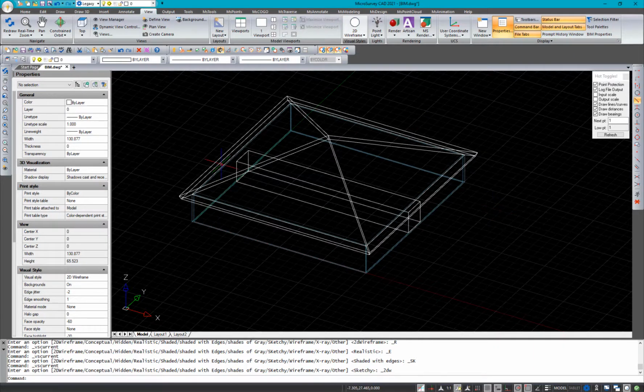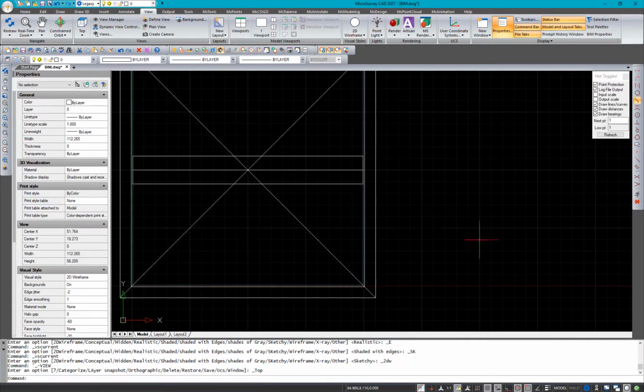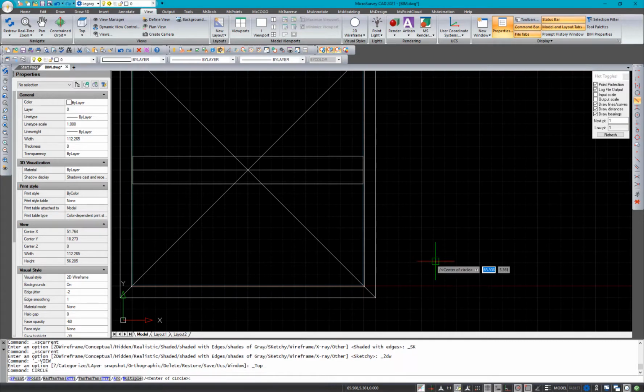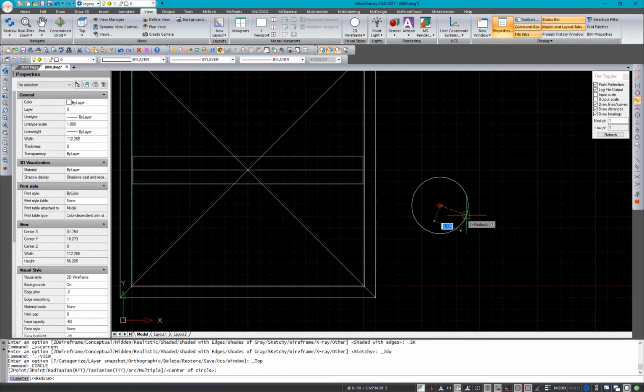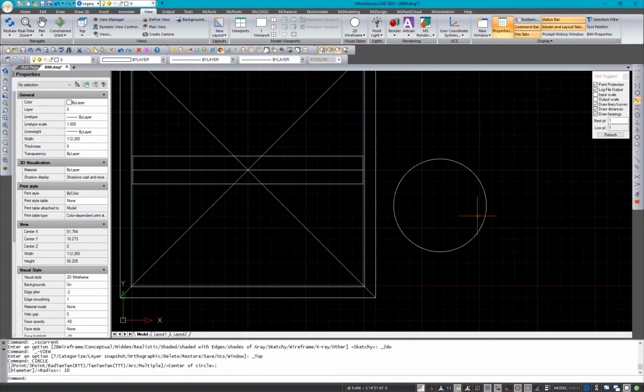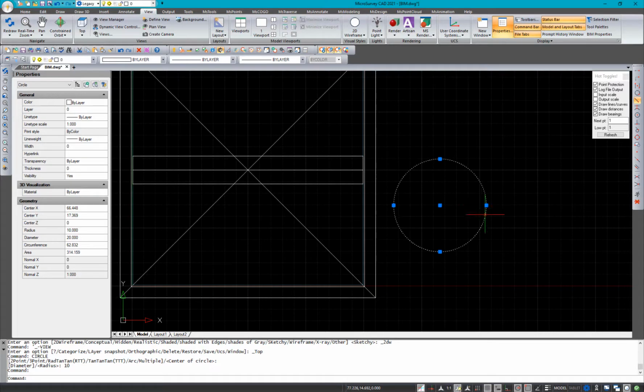Something new that is in IntelliCAD 10 now here as well. We have dynamic input, so you can see this here. It's started typing in the drawing pane next to the cursor. So now it will show various things next to it as I draw. Like I've got the dimension here, and say I want to input a dimension of 10 next to it. There, it enters it right there for me. And if I hover over top of some of the grips, then it will start to show me distances around as well. So that's some quick drawing review tools for you there.